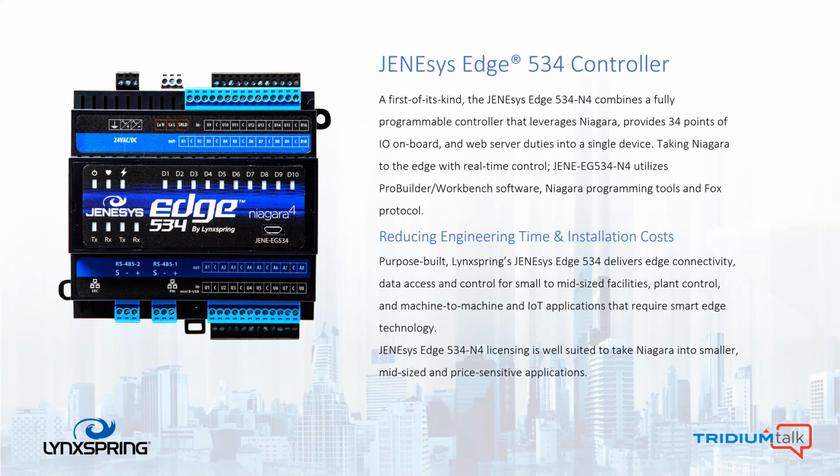The physical aspects of a 534, if you don't know already, the 34 indicates the number of I/O inputs and outputs. It has 16 universal inputs, 10 digital outputs, and 8 analog outputs. The communication ports available are RS-485. They can be BACnet MSTP, they can be Modbus, they can be other serial type networks, which are supported by the standard Niagara drivers that are available. Okay, so this is fully Niagara. You can place the drivers that you're commonly used to in integrating other disparate systems with the Edge 534.